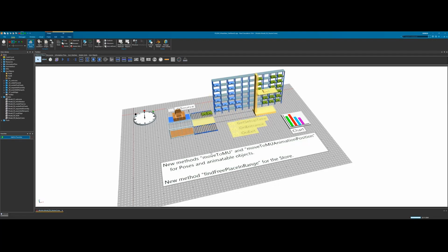If you don't add this bit of SimTalk code, it would simply mean that the animation would finish this one movement before the failure becomes visible by the stacker crane not moving anymore. So yeah, I would argue it may not be necessary to even do that. But yeah, if you want to, then you would have to interrupt or pause the pose movement.